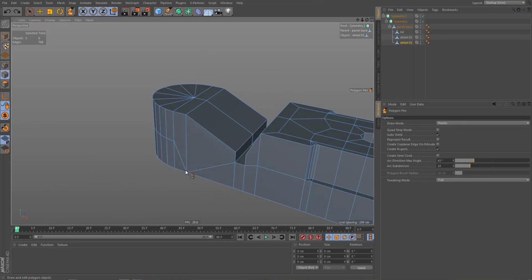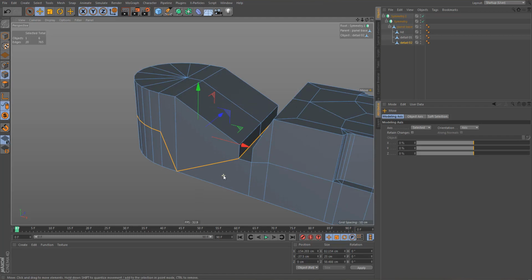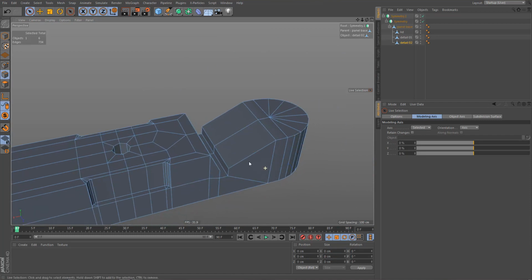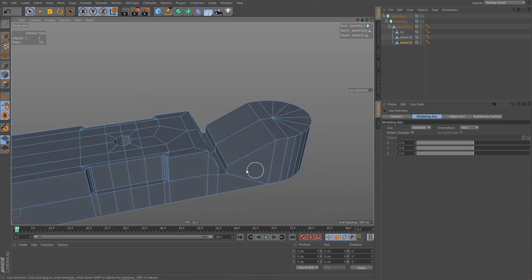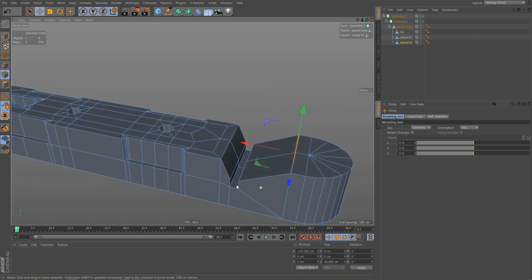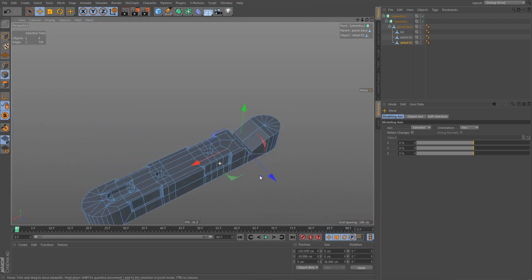and these ones. Select these edges. Just make sure to deselect these ones again. And dissolve these edges. And up here, we could break the phong shading on these. And same here, you can see the shading is a little bit off. So let's break the phong shading to fix that.